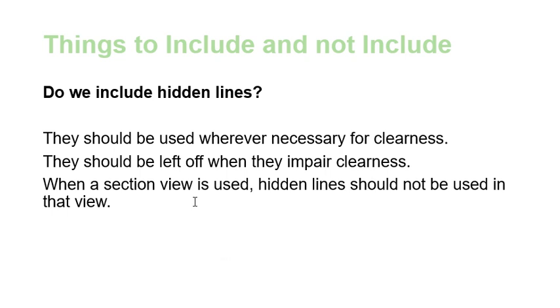Otherwise, if you put all kinds of dimensions, it'll be so cluttered. So clear lines, visible lines. What am I saying? Visible lines and hidden lines. That depends. Hidden lines depend on what you want to do. You can use them if you need clarity. You can leave them out if your assembly shows everything it's supposed to show, all the components. It depends on how complicated your system is. You can leave out or show the hidden lines.